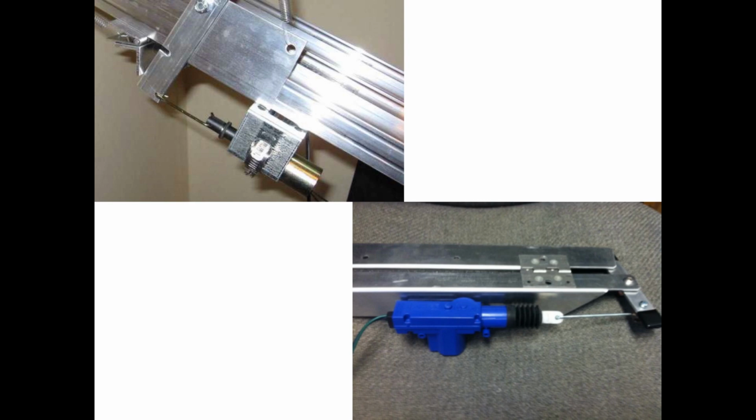So, why use a solenoid start gate? If a person is manually pulling the start gate's release lever, there can be some inconsistency in how they do so, from heat to heat. This inconsistency can actually cause some variation in vehicle run times. Using a solenoid start gate can give a much more consistent start to each heat, greatly reducing the chance that start gate operation will affect the vehicle run times.